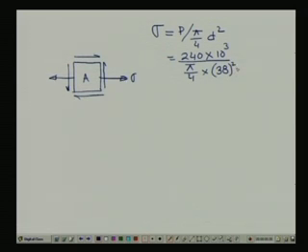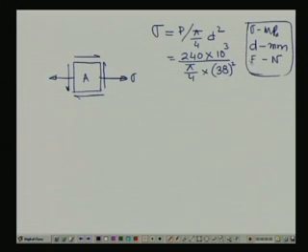One thing you must remember, and I am telling you once again, that in the design you put the stress in megapascal and the dimensions in mm, then forces will be in Newton. So, do not bother about changing to meter, etc. Just remember these three things: force you keep in Newton, dimensions in millimeter, stresses will be in megapascals. Automatically it will come out, or you can also verify.